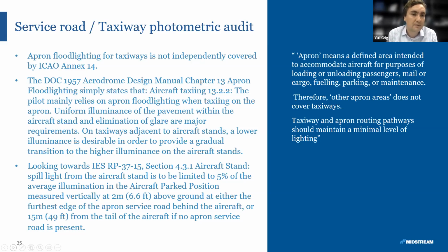Now, Doc 9157, the design manual, says this under section 13.2.2, aircraft taxiing: the pilot mainly relies on apron flood lighting when taxiing on the apron. Uniform illuminance on the pavement within the aircraft stand and elimination of glare are major requirements. On taxiways adjacent to aircraft stands, so this is maybe a taxiway behind it or through the aircraft stands, a lower illuminance is desirable in order to provide a gradual transition to the higher illuminance on the aircraft stands. So that's what that document says.